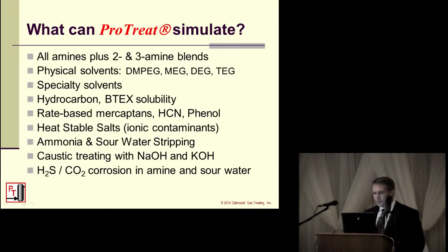Hydrocarbon, BTEX solubility in the solvents, and additionally we've recently introduced capability to do caustic treating with mercaptans, HCN, some nasties from refinery services like heat stable salts, phenol, and ammonia and sour water stripping.